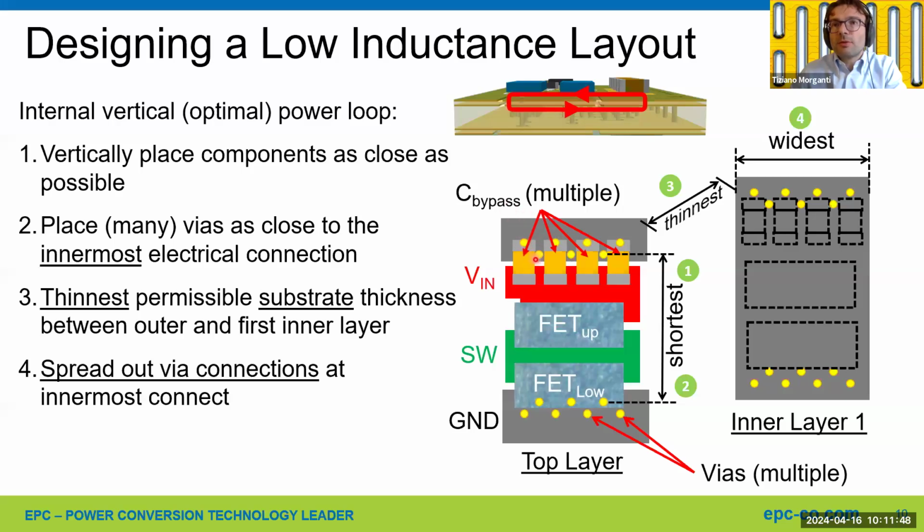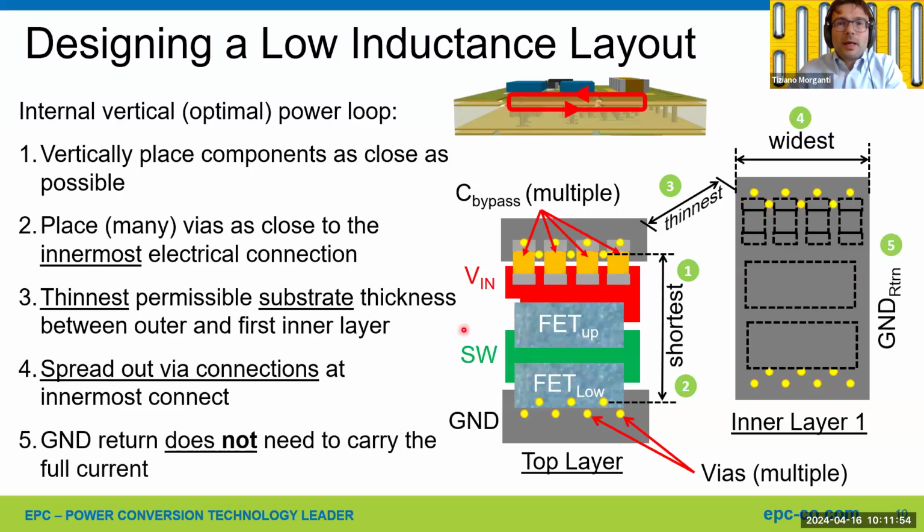It's better to use multiple small capacitors instead of one big capacitor. And to be noted, the return plane here is required for the return of the high frequency currents during the switching transient, but it's not mandatory that it be sized to carry the full current of the converter.